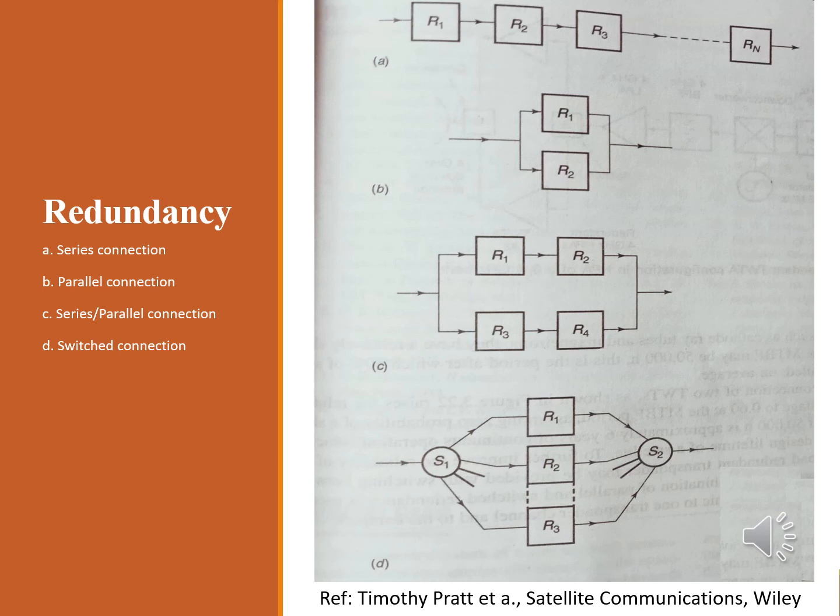The switched connection arrangement is also referred to as ring redundancy, since any component can be switched in for any other component. And here you can see switches S1 and S2. They are a little more complicated than as shown, so they afford the choice of multiple paths in and out between the input side and the output side. And the important point here is that the active devices used have sufficient bandwidth and power output range to be able to handle any of the channels that might be switched through them.